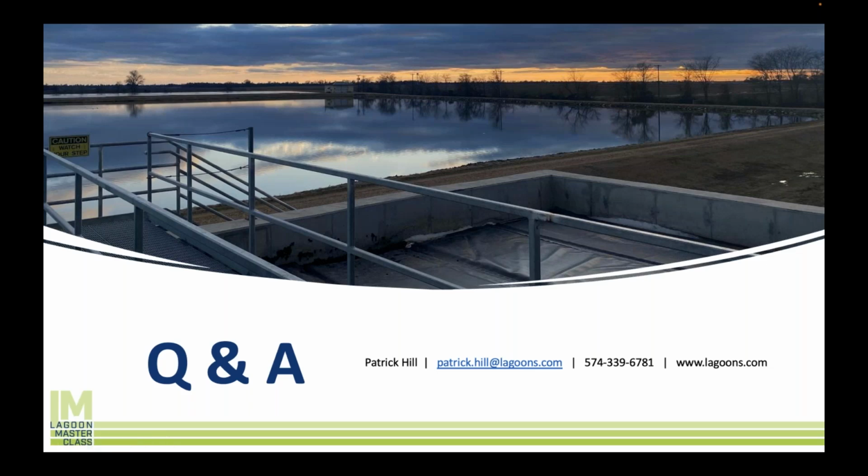All right, Patrick, I have one for you. Will pond dye work like it does with algae at covering a lagoon surface? So yes, pond dyes can be effective. A couple of things about pond dyes. One is that pond dye is less effective at killing algae that already exists than it is at preventing algae from existing in the first place. It doesn't attack the algae, it just attacks the sunlight's ability to help the algae photosynthesize and thrive. So it's a better proactive than reactive approach to algae.